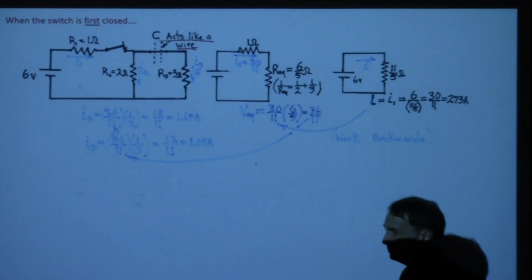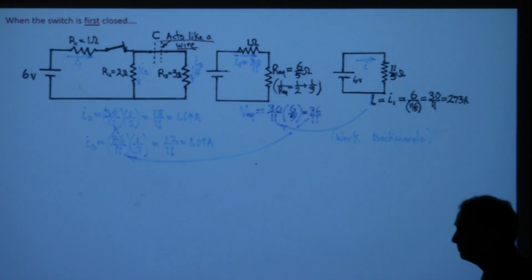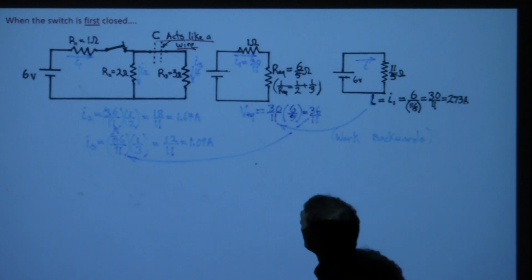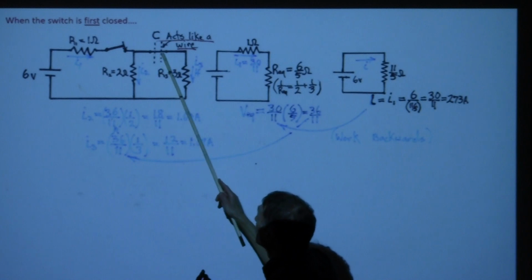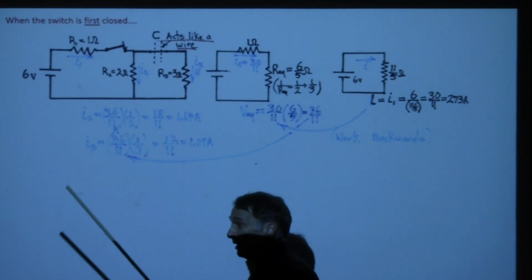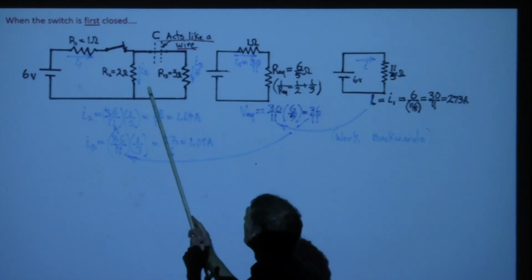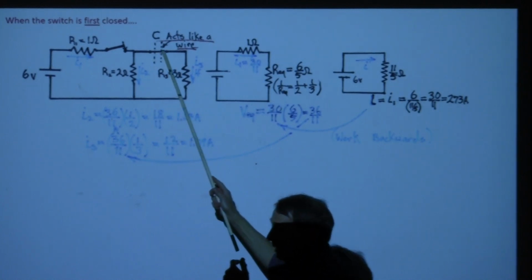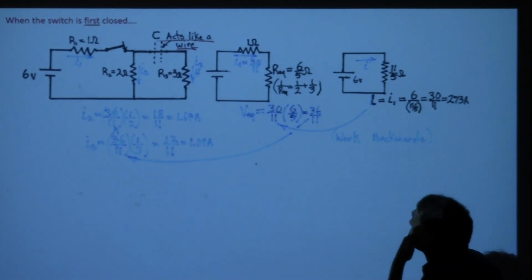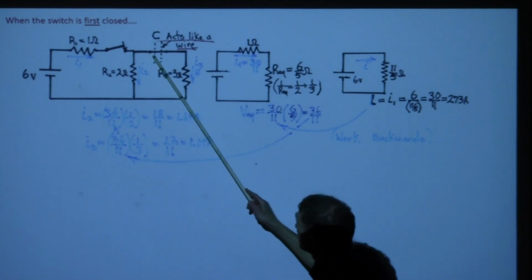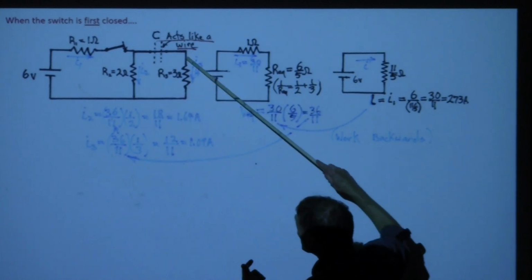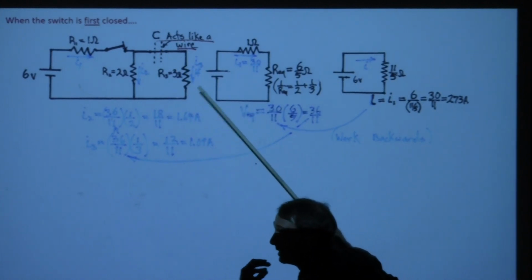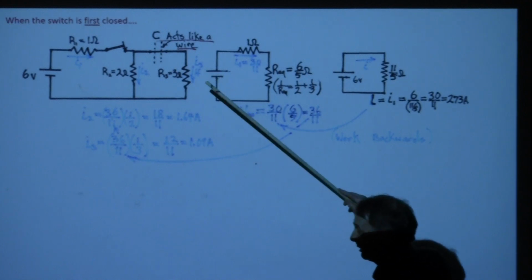Why do we count the capacitor as a short circuit when we just flip the switch? Well, there's no voltage on the capacitor, so there's no voltage drop. Right. Also, the charge is really starting to pile on. It's like saying, hey, we've got a big bus here, and nobody's on, so you can go ahead and climb on. So the idea is that it more or less does not obstruct the current flow at all. The resistor, though, is probably going to control the fact that there's not a lot of current jumping on the bus.